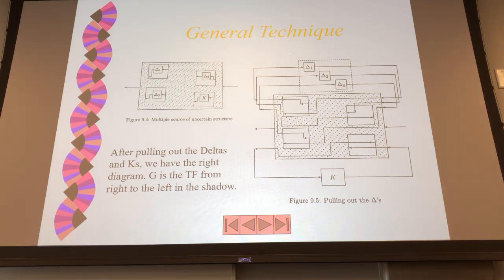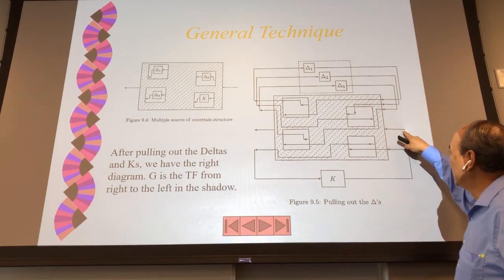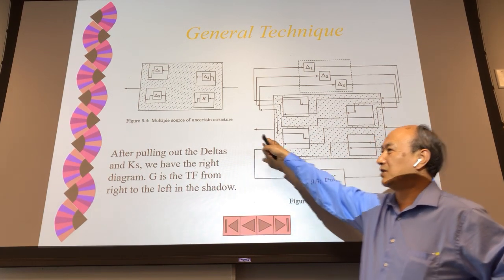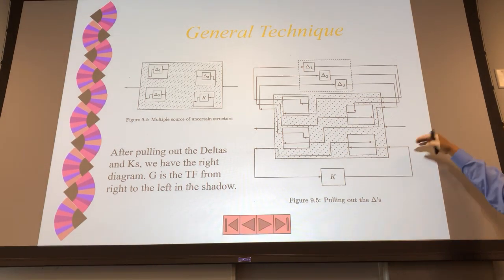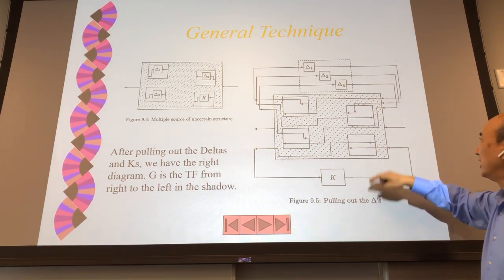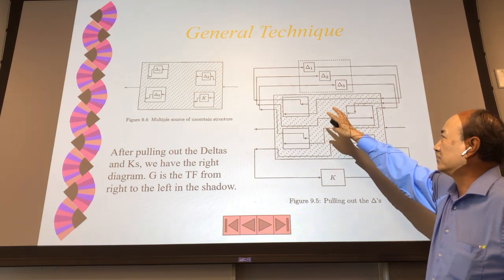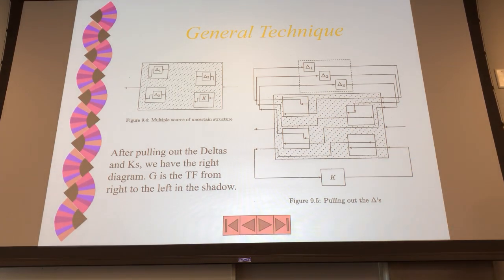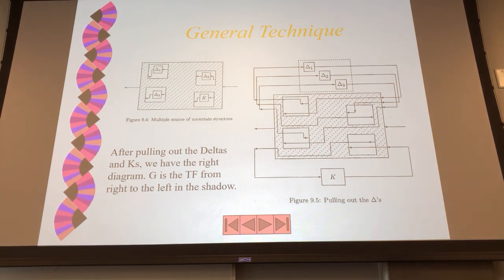I also want to pull out, okay? I also pull out. So this is something we want. And this is W, this is Z. So D is for performance assessment. So then this is for feedback and control. And this is the internal connection of those uncertainties. I pull out the uncertainties. So once I can pull out, what do you see? This delta becomes what?